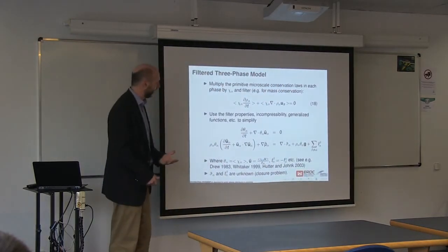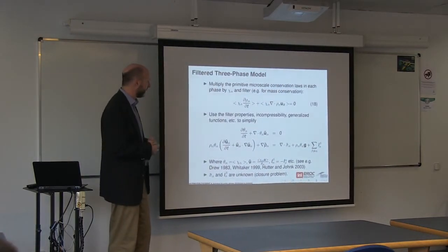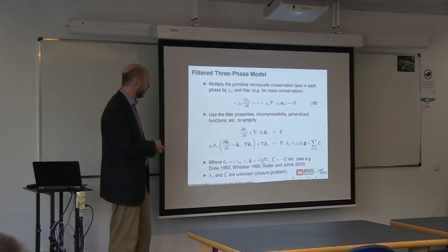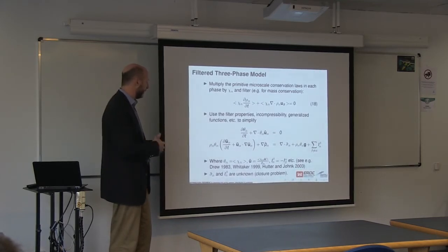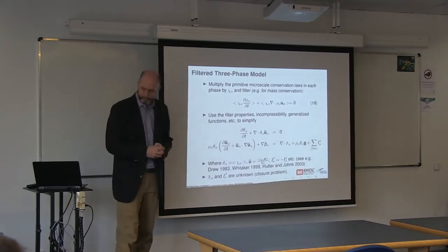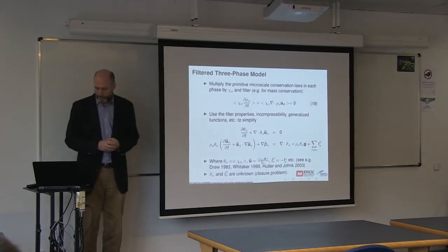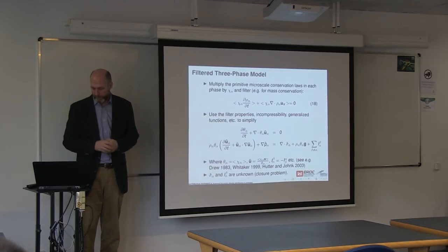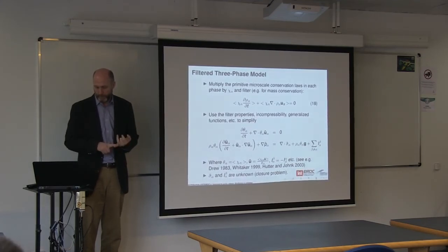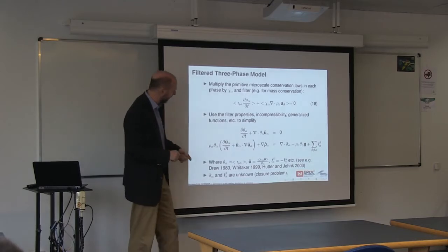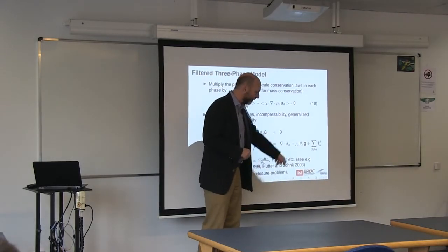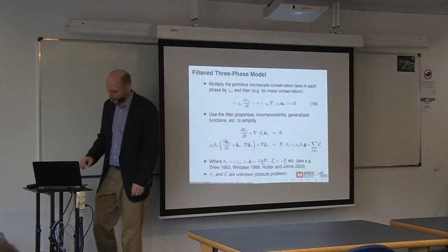So they're the averaged contributions of drag: momentum lost from the fluid phase into the solid phase, and then the matching term in the other direction. So in this slightly simplified form, I get the interface terms needing closure, and you also would need to come up with a new macroscale viscosity or stress tensor.